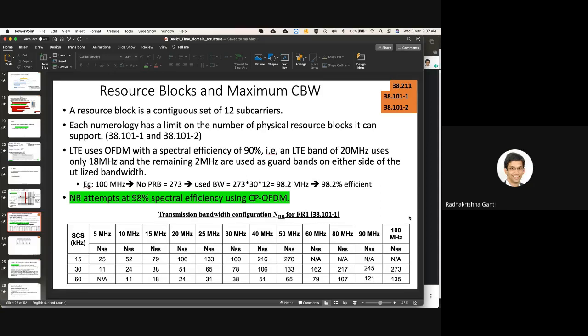But as time progressed, there were a lot of developments on the device side, the power amplifiers, and multiple different types of power amplifiers which are more linear. And people also understood how to optimize this for linearity. So what has happened is, even now, single carrier OFDM has much better PAPR than CP OFDM.